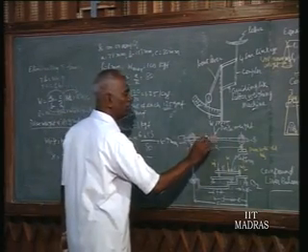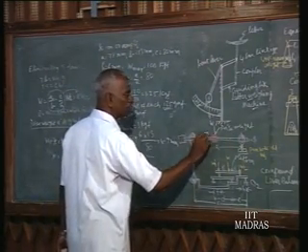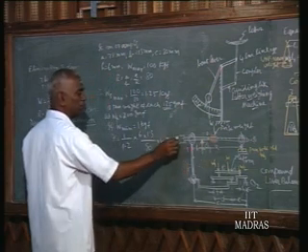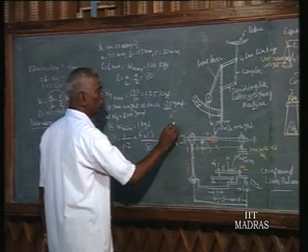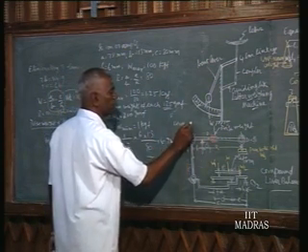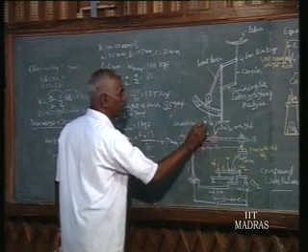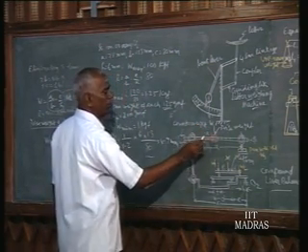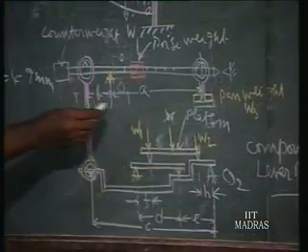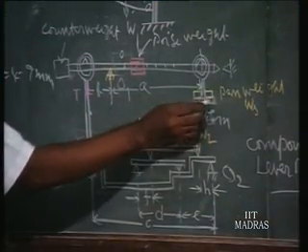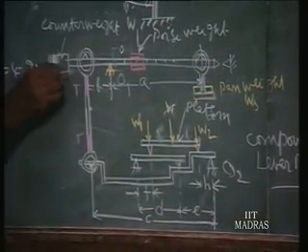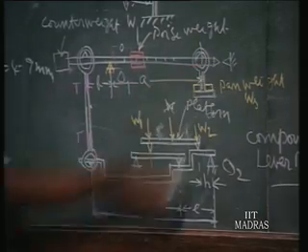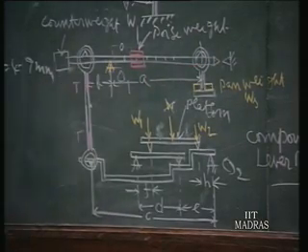When it is 0, it will be standing here. At that position, this is the counterweight. The counterweight is fixed in such a way that when there is no weight here, with the poise at 0 and no pan weight, only the holder, we move it until the lever stands against the reference mark and fix it there, as 0.